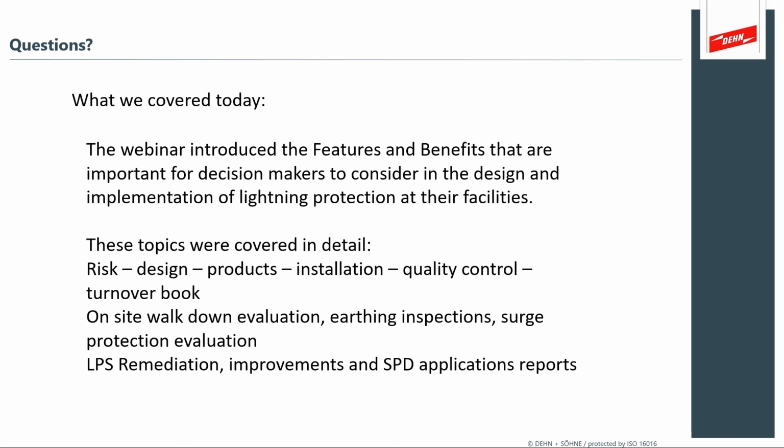I just want to add that if you have technical knowledge of the proper measuring techniques, you can use this clamp meter to measure loops and multiple bonds, ground bonds, as long as you have that knowledge of how the loop is supposed to be completed and what exactly you're measuring.